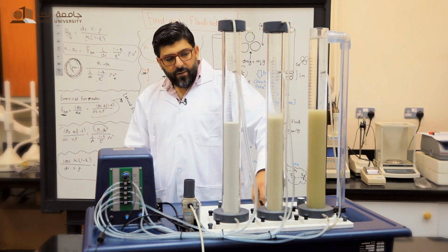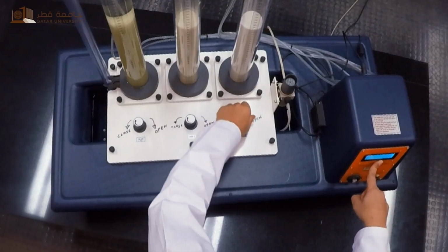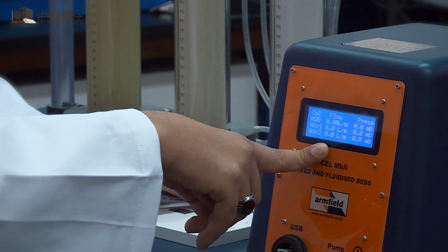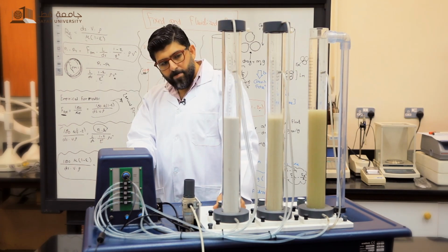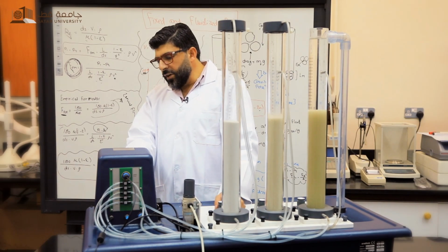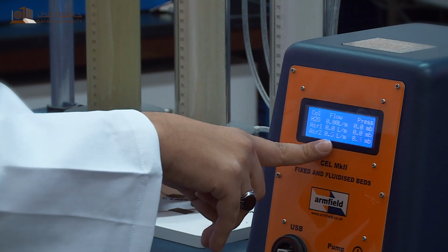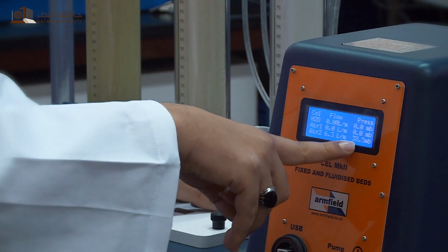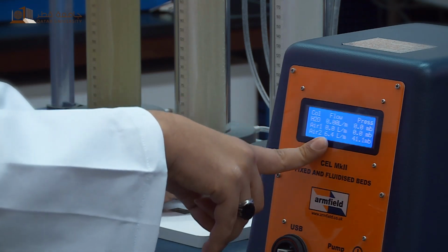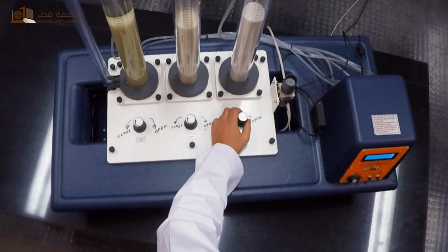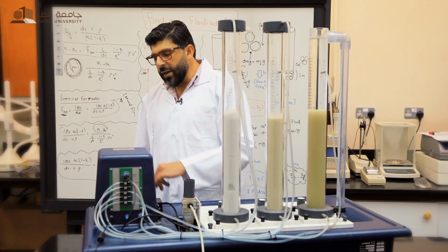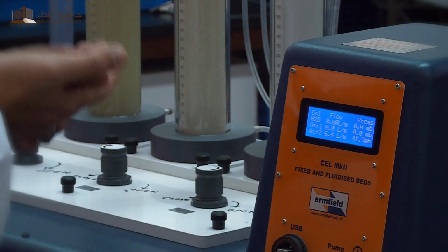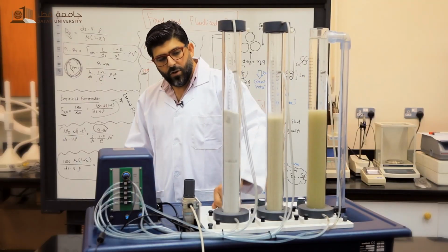Also for the third one, air 2, it is the same. There is an increase in the flow rate and the pressure drop increases until it reaches fluidization. Once it reaches bubbling fluidization, the pressure drop becomes almost constant, no more increase. So you need to take the height, the flow rate and the pressure drop every time until you find the pressure is almost constant. So this is all your raw data. That's it. Now I'm closing the experiment.